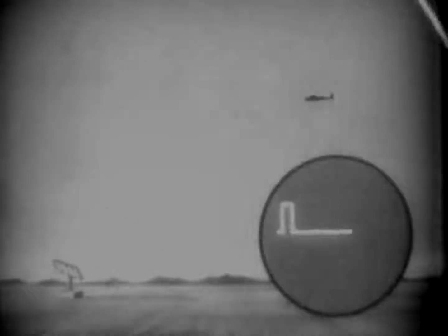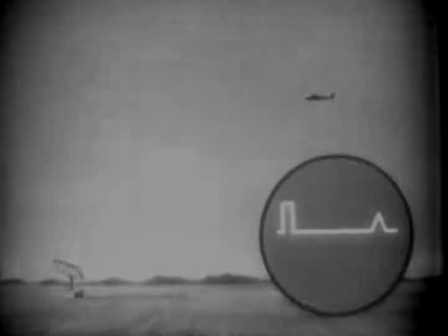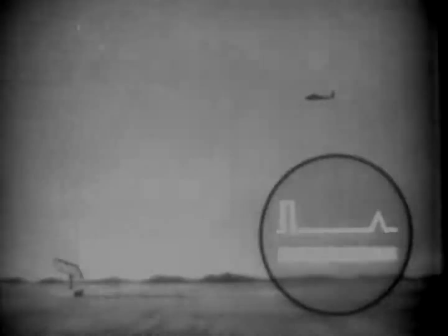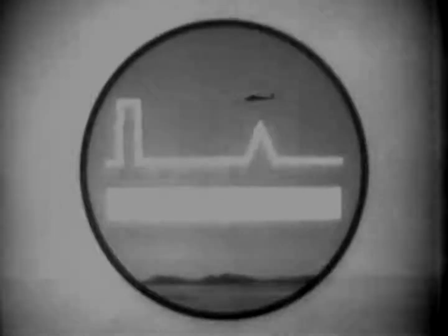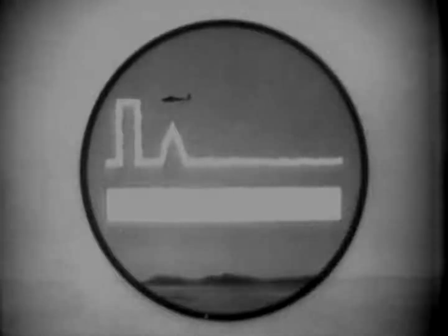So much for measuring azimuth and elevation. You'll remember that to measure range, you need only a single pip, A-scope, and the distance from the pip to the main bang represents the range of the target. As the target approaches your set, its pip approaches the main bang. The baseline, or sweep, as we've said before, represents the full range of your set.